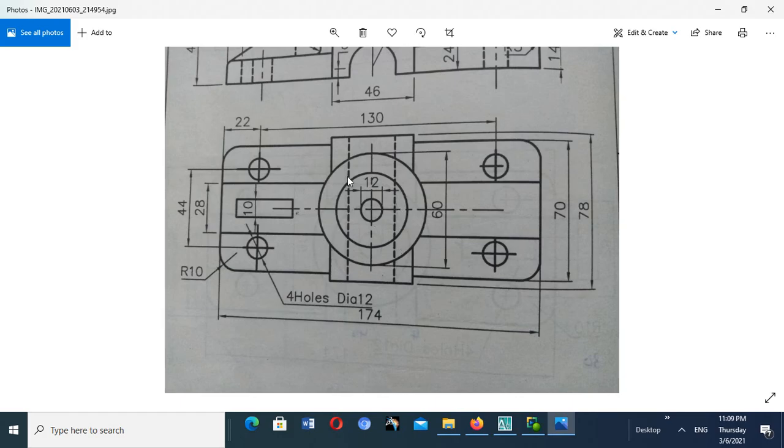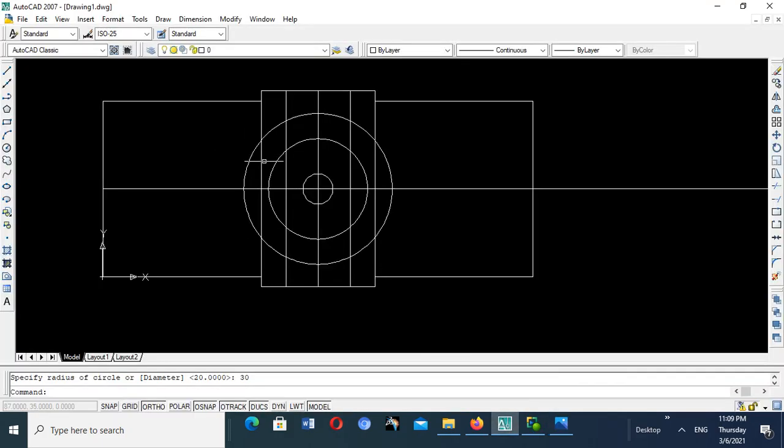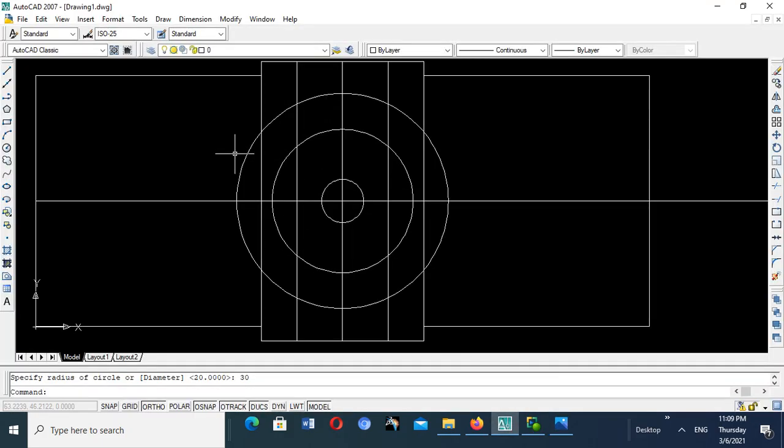The line type, to show hidden detail. So we can go ahead and do that. So let's first trim this unwanted line. So we go to our AutoCAD. I told you already that the short command for trimming is TR and enter.